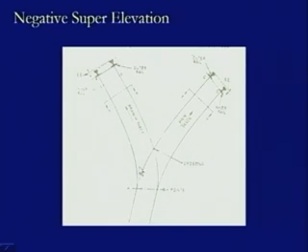Now, if we are raising this rail in this section and if we have to raise this rail in this area, then it is not feasible to do both things simultaneously. This is where, when we provide the super elevation for this curve, it will act as a negative super elevation, because it is going up, whereas in this direction it has to go up the other way. So, it acts as a negative condition for the other track, and this is how it is termed negative super elevation. We have to look at these values of negative super elevation and design the connectivity accordingly. We will be looking at how we do this design.